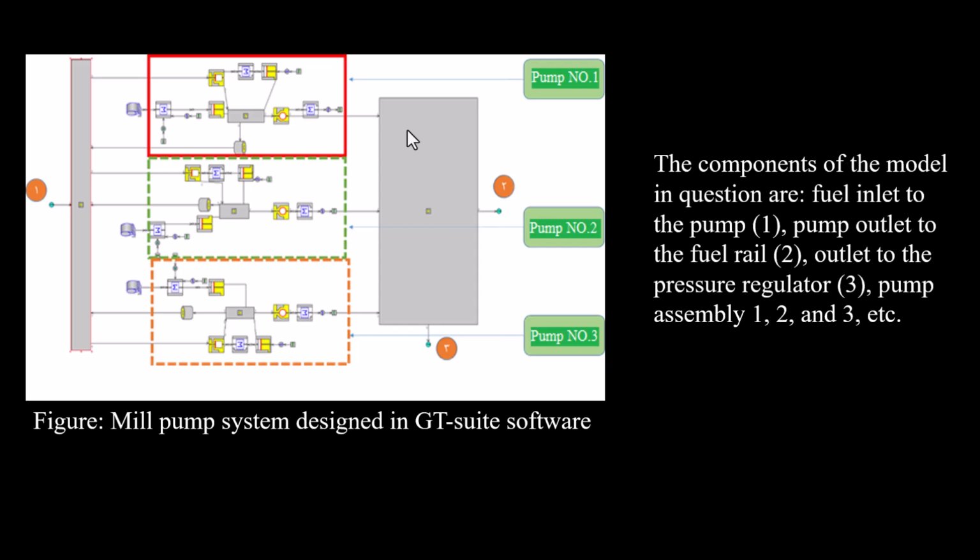And the mass represents the inertia of the mechanical system, such as the piston mass or parts of the pump's internal mechanism. It helps model pressure fluctuations and mechanical vibrations. Usually you define the mass as a mass component or consider it within the reciprocating assembly.